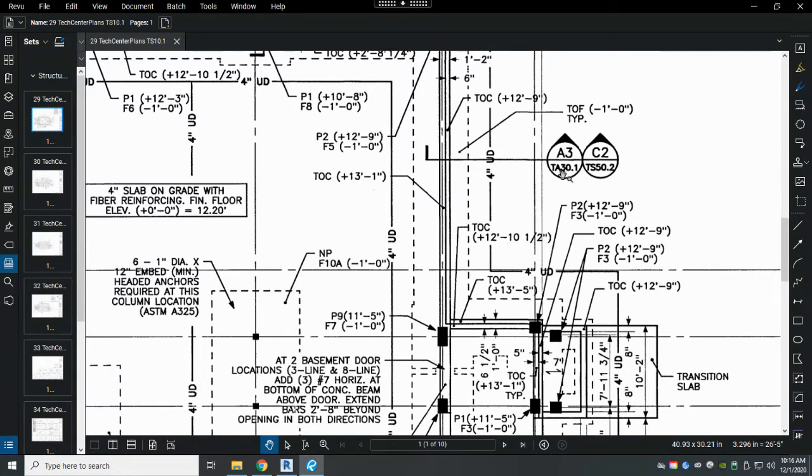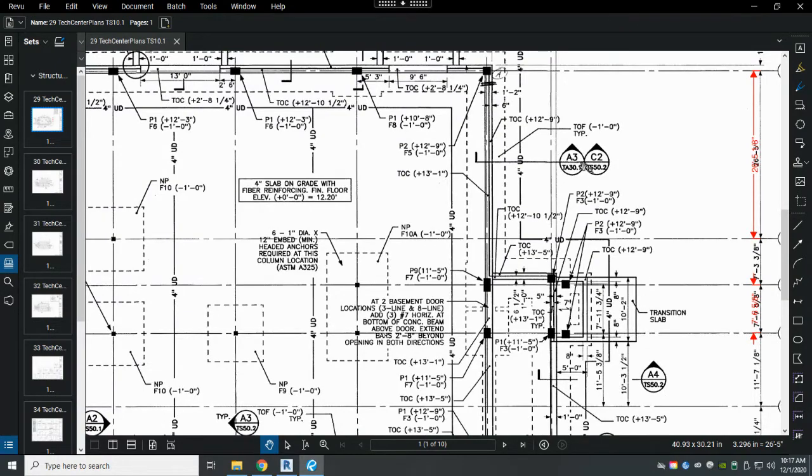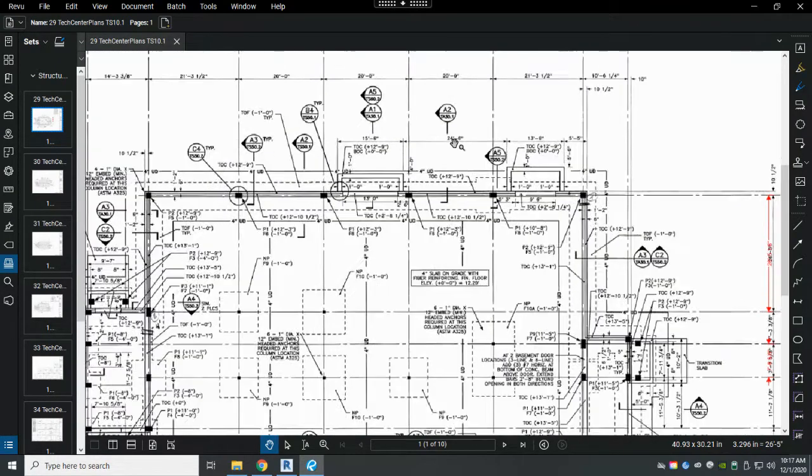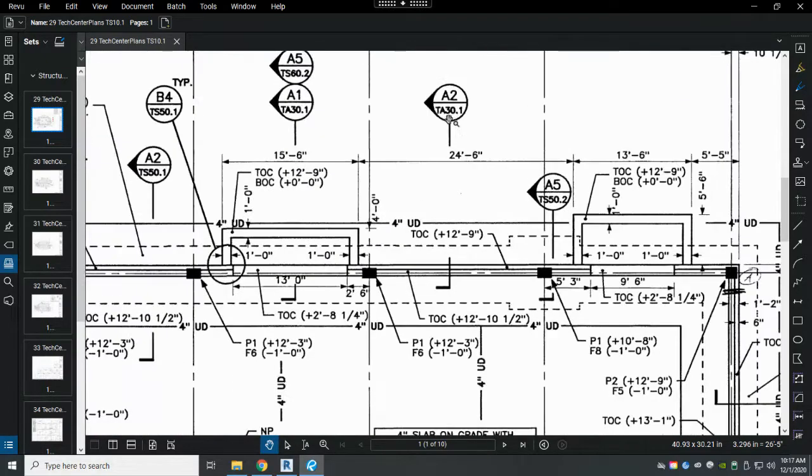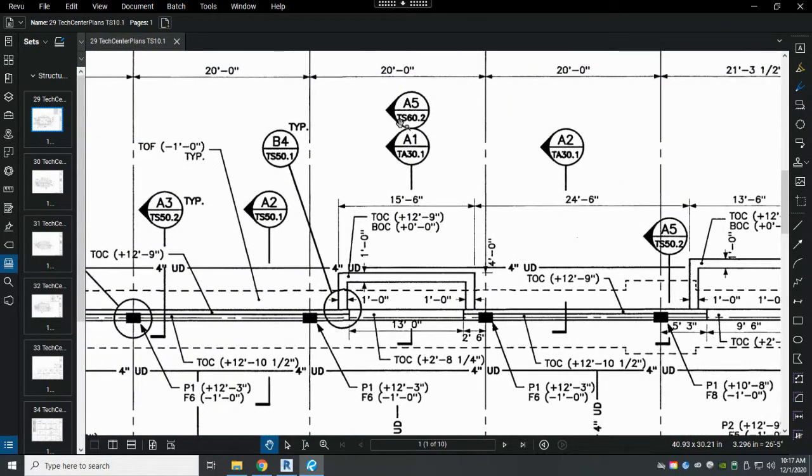The architectural version is going to have general finishes called out, and will indicate to reference the structural callouts for any structural member information, and the structural callout will have all of the structural information in it, like bracing, steel and structure. So that's why there are two callouts there. It's to reference that we have it being shown in two different places in the entire set. So pay attention to whether or not it says TS or TA to know where to go within this set. The TS are the ones that are going to be part of the structural set.